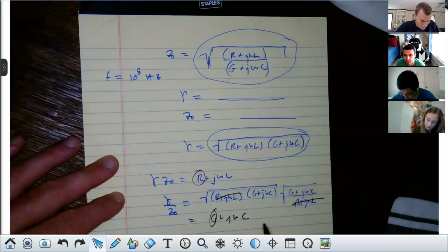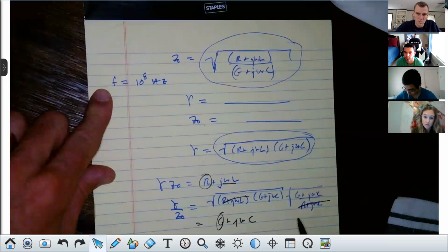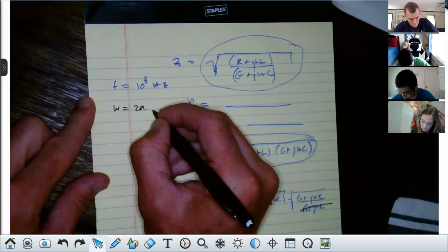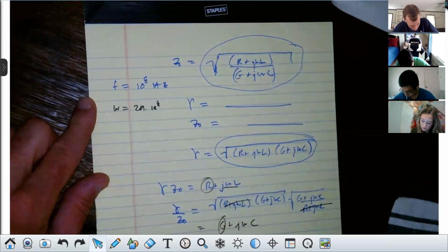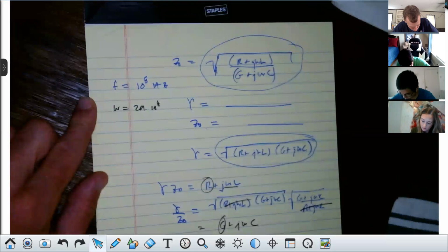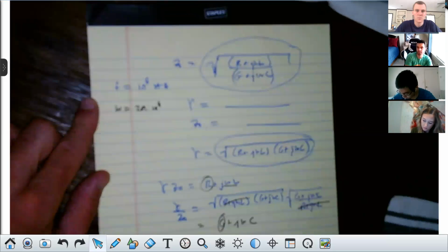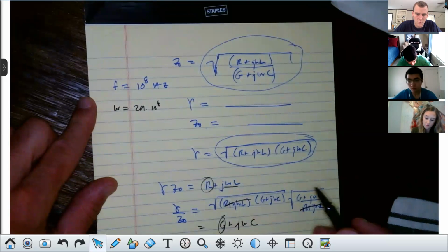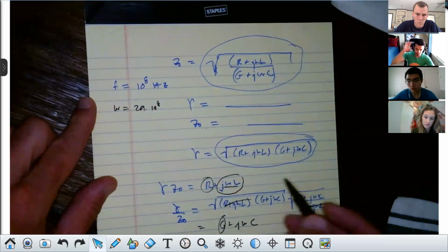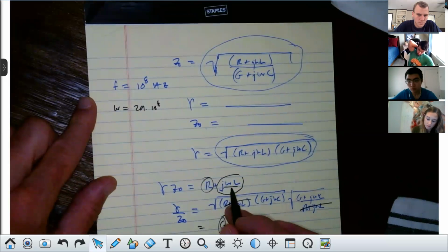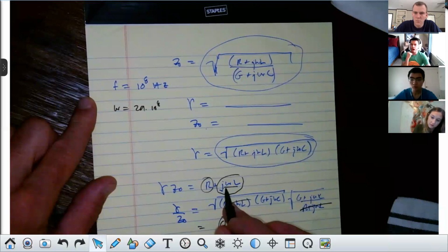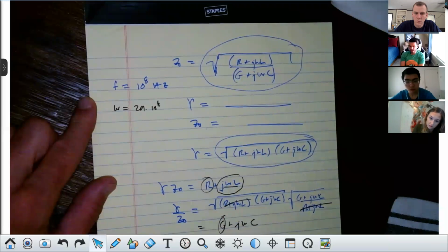Now, when I talk about omega L, if F is 10 to the 8th, omega is 2 pi times 10 to the 8th, right? Are you with me? And if that's the case, when we have J omega L here, we simply divide out the imaginary term by J omega and we get L. Do you all follow me on this, class?